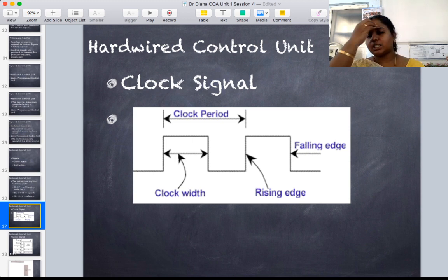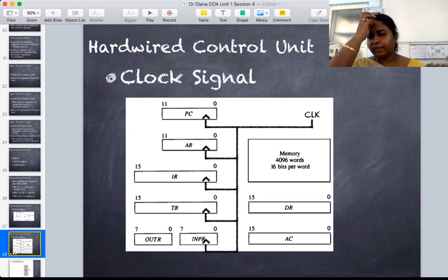Now, this clock cycle is given as an input to all the registers. We have seen this is our basic design which we designed earlier. We have some registers here, and all of these registers receive a clock cycle. The data register and the accumulator register also receive the clock cycle. The clock cycle is represented using a triangular arrow which is put inside of the register.